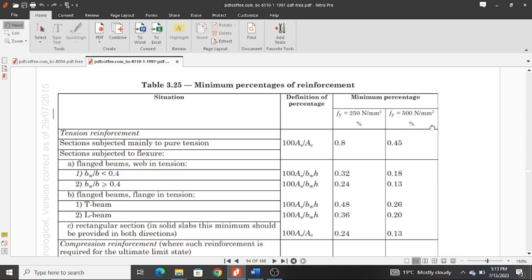Basically, in my country, this one we treat it as the yield strength of the ribbed steel bars, and this is the yield strength of the round steel bars that we normally call R, and these are the ones that we normally call T or D. This is in Kenya, so in your country, if you're not in Kenya, this might be different.